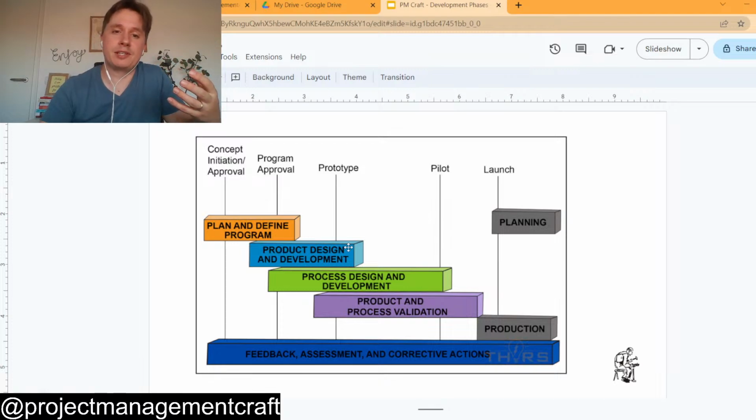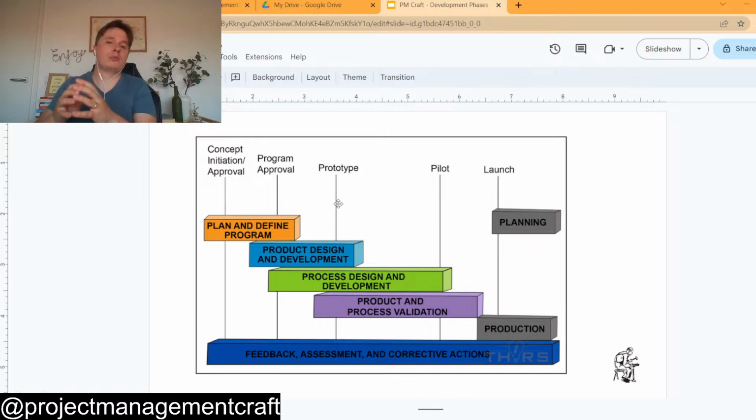What's very interesting here is that in automotive they have what's called the design validation part, where you take those prototypes and put them in testing under qualification tests, where you check performance, durability, and a lot of other items to make sure that you can confirm your design work. And of course, in parallel, you're already developing your process, looking at the design, and at the steps that you need to have this in serial production.